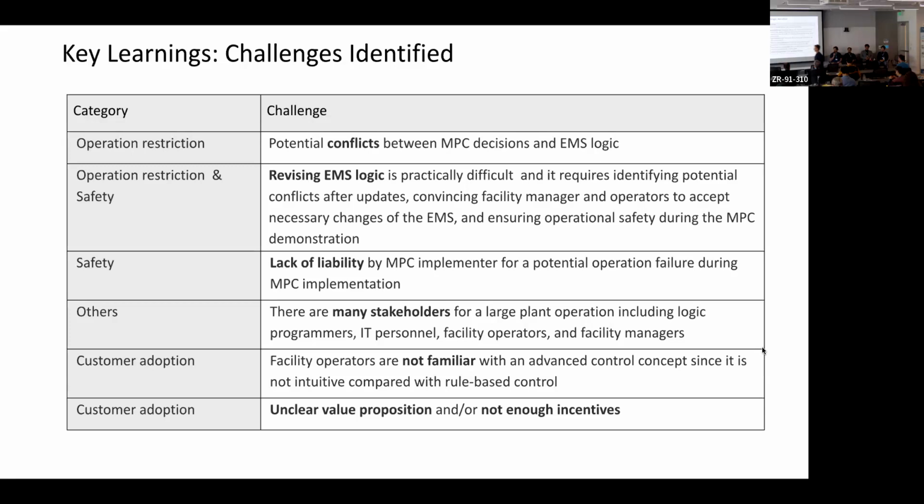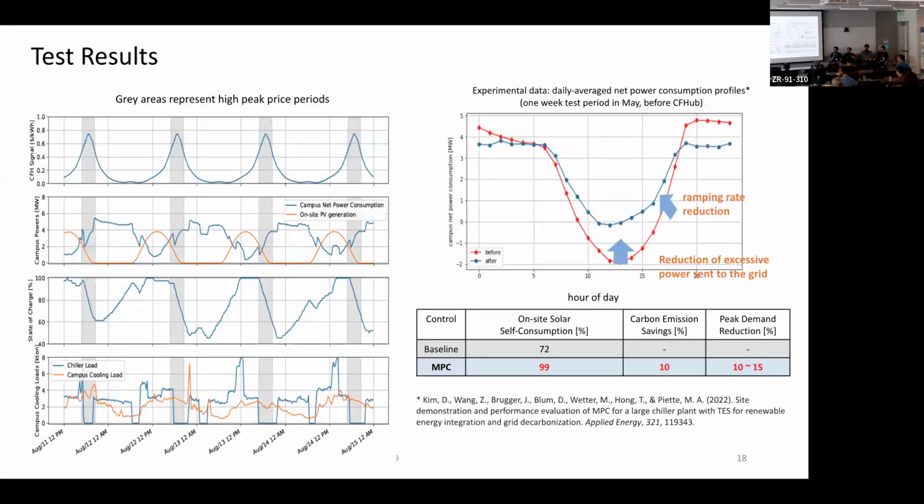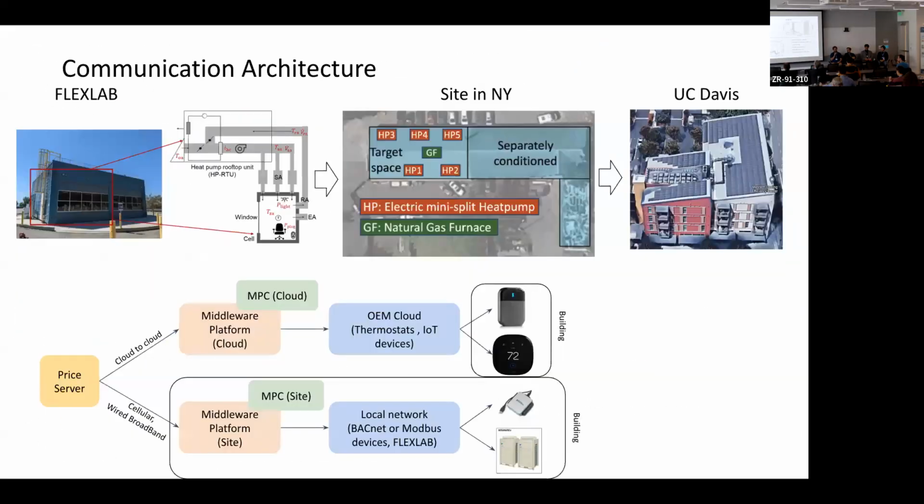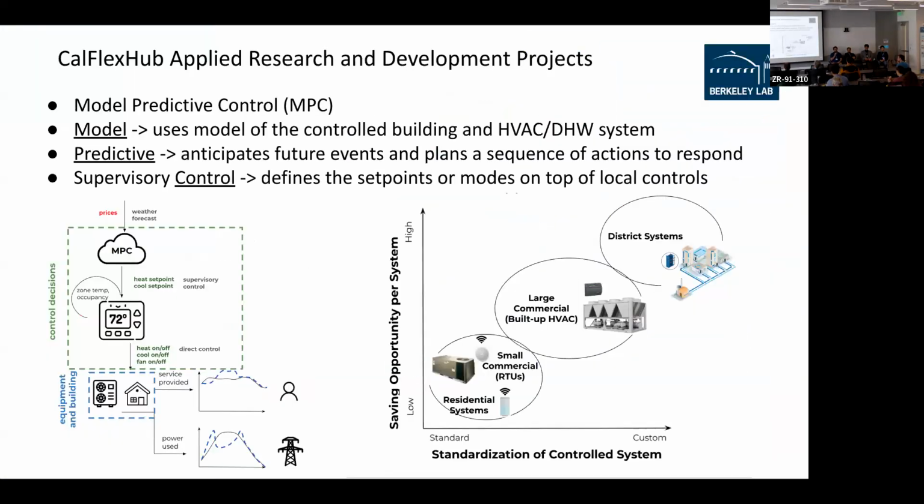So for our project, the water heating model, we're using a first principle model for the water dynamics within the tank, and then just a simple RC transfer for the tank shell and the other properties there. Through our lab testing, we've been able to identify the capacity that the heat pump actually puts out, as well as the electric resistance heat. So all of those parameters are put into our model.